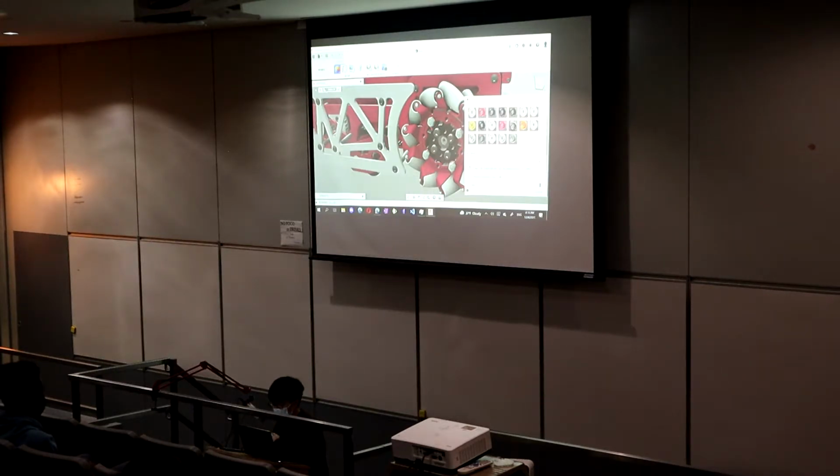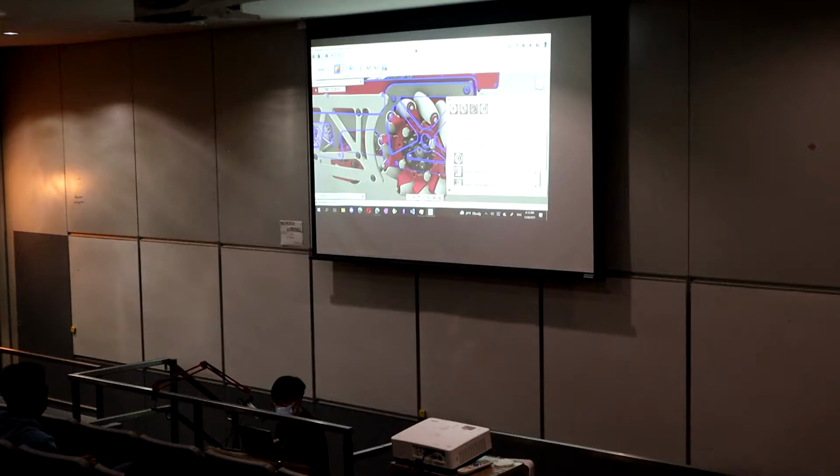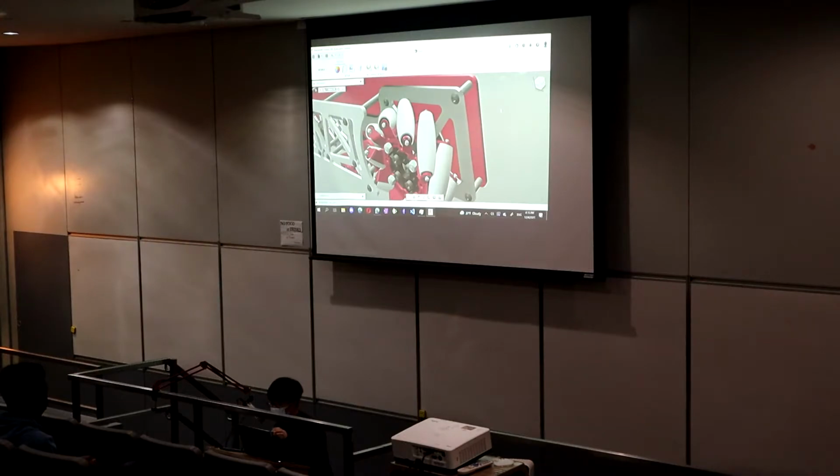We can browse a variety of appearances. Metal is going to be a really popular one because a robot's made out of metal, right? Then we can click aluminum in this menu. I'll try to make this bigger because on the projector it's a lot smaller. There's a variety of colors and materials we can do, right? I like to use aluminum satin for these plates on the robot. You can automatically see a different texture. You can see how this part is lighting up, right? So you get that metallic appearance.